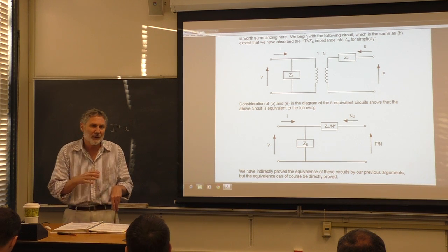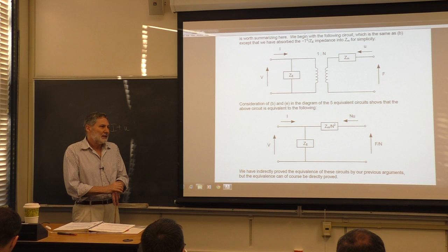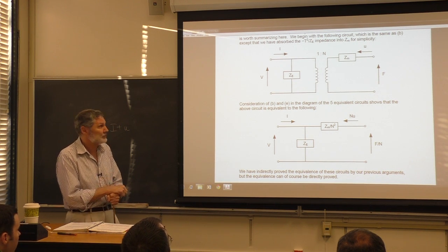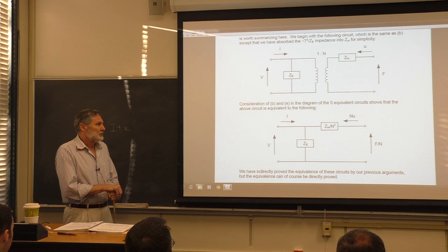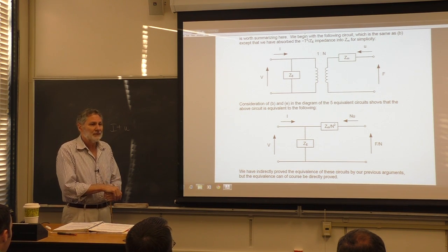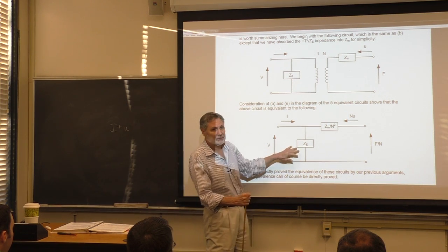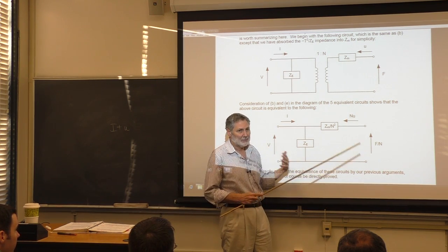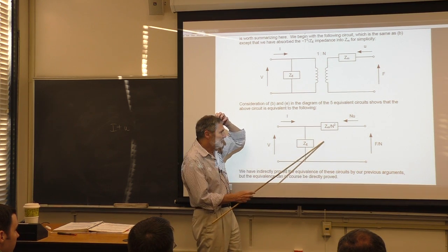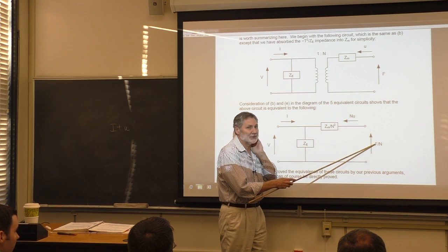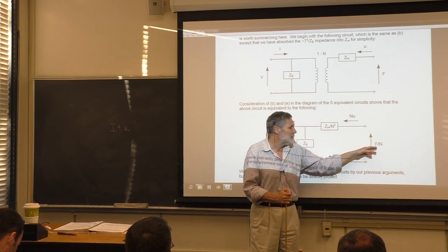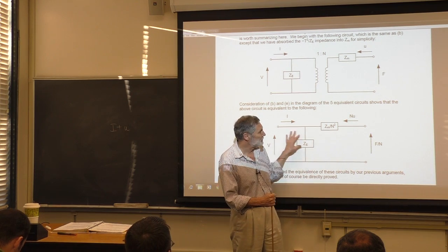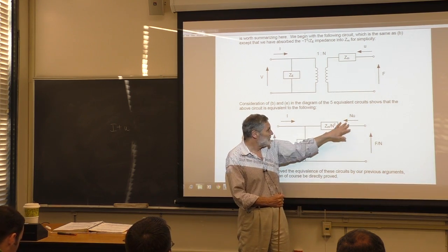They tend to think this way when they're coming up with equivalent circuits. They actually start with a transformer in there, because that's what the transducer is doing. And then almost always you want to eventually eliminate it so that we can get down to a real, purely electrical circuit. Then you solve for this, and here's the basic idea of this course really. Once you solve for this, you can go back and find the force. If this is a transmitter, you could find the force that's causing the acoustic radiation. Once you've used Kirchhoff's laws to solve for this, you can find the currents involved, the velocity, and the force.